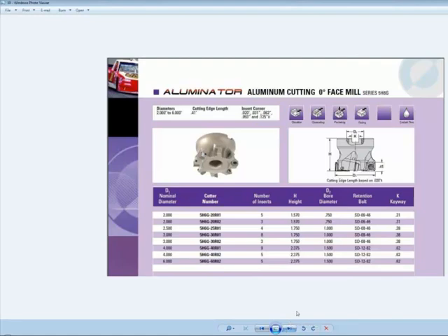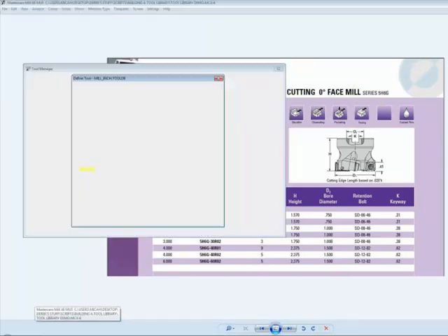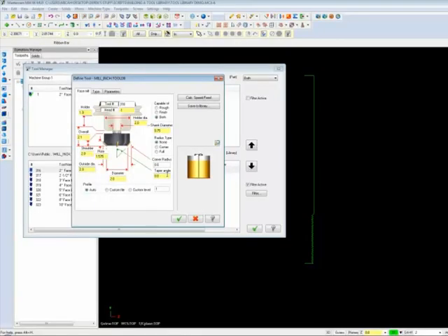That's what I was saying. I didn't know if he was talking about a 90 degree chamfer tool or a 90 degree spot drill, compared to a 90 degree on this, because this is where a lot of people go in that face mill configuration and put 90, thinking it should be in that direction. And it's not correct, and it gives you an error. So, like you said, is the zero actually the correct answer?